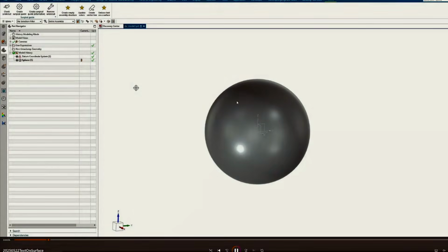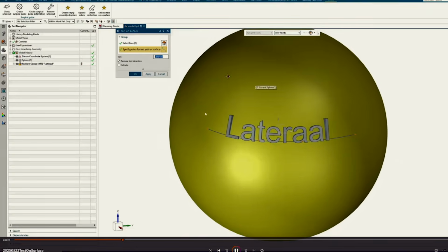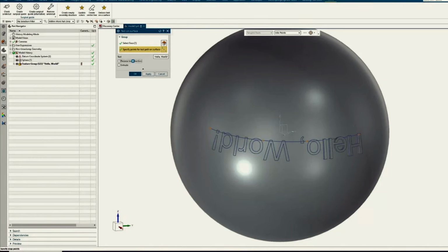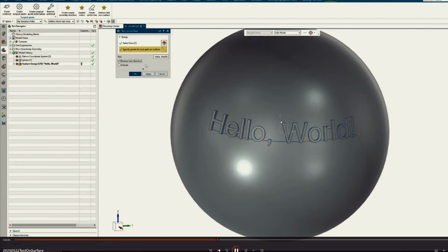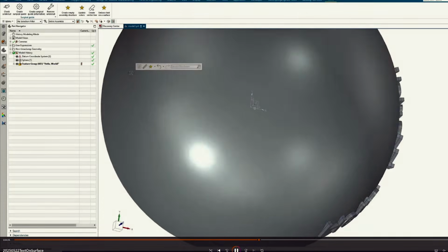So I've used the demo here of a globe or a sphere we can generate text on. Basically on the sphere, you determine a few points, you draw a line on it, and then the script automatically generates the text on the surface. And then if you add that to the surgical guide, it gives a double check for the surgeon, and it gets printed onto it. So that's how you create text on a doubly curved surface, and the practical application for it.